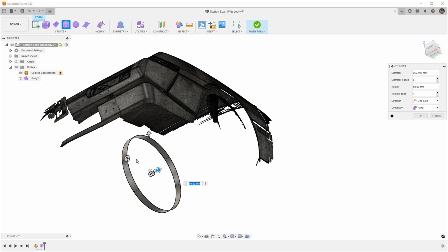But one thing I do want to do is increase the number of divisions to something like 16 for the wheel opening. And the main reason that I want to do this is because when dealing with a cylindrical form, it is much harder for us to get that form to be nice and round, or at least mostly round, after the fact when we start adding edges. So increasing the number of edges that we have in this circular form or this cylinder is going to help us downstream, because we don't have to worry as much about inserting those edges. We can just tweak them wherever we want them.